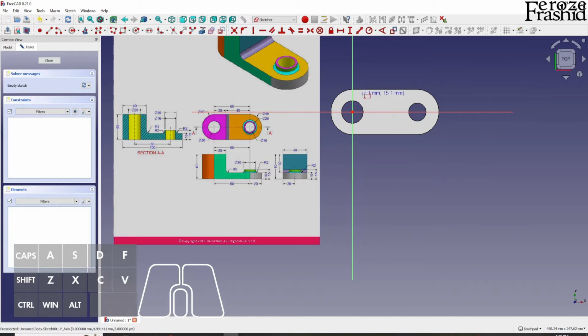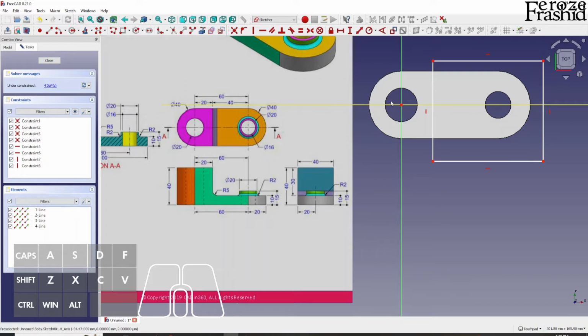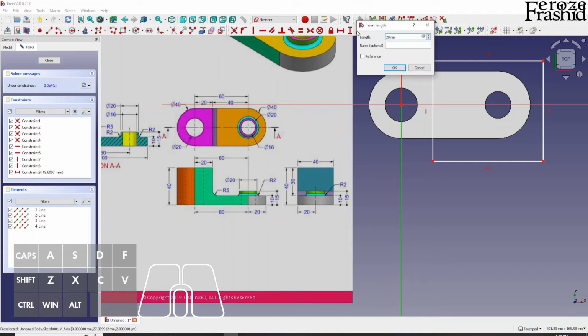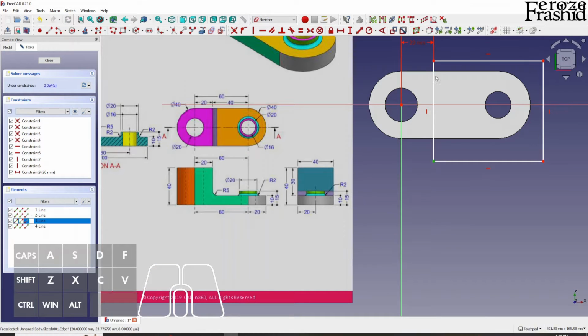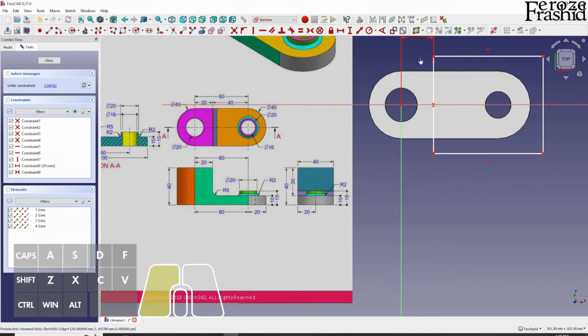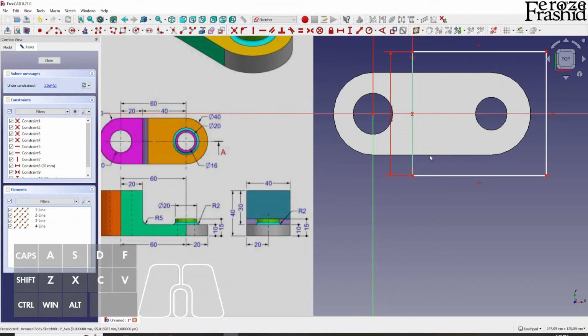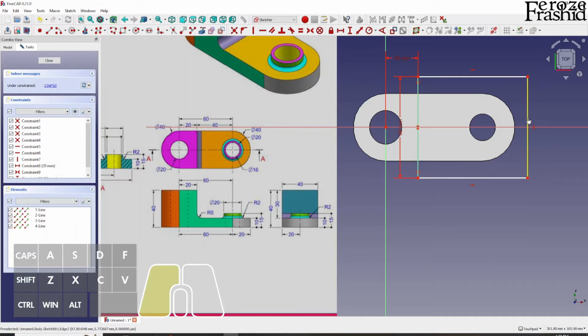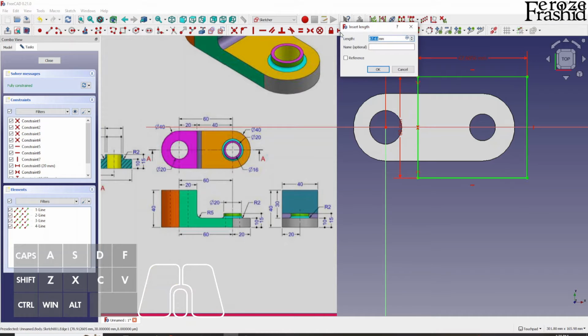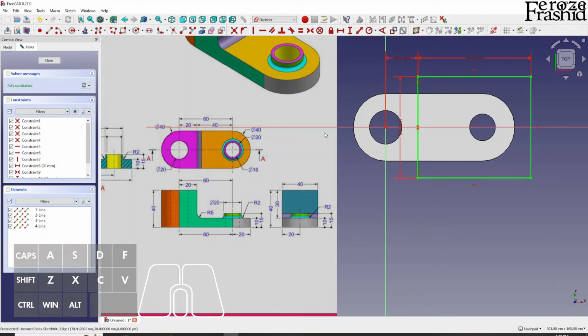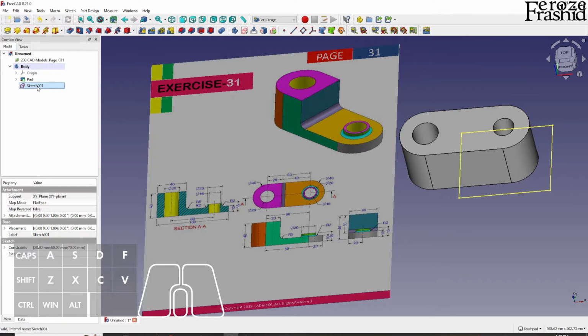So this depression will be a cut, and the distance between that cut and the center is 20. I want to keep this distance 20, and then it does not matter how wide this cut is. So I want to make it symmetric first, and then make it a wider body, say 60. It doesn't have to be on this edge, as long as this edge is outside of this body, I'm fine. So I'm going to say this is 70. It's a wider body. So that's my cut that I'll be making.